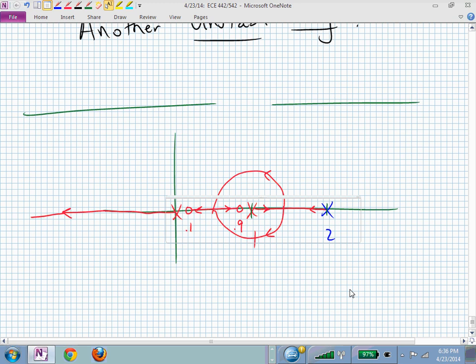And probably if I would squeeze those together and make this one not 0.9, but maybe 0.7, and the other one maybe leaving it at 0.1, my percent overshoot would probably improve. But I need to be careful that I don't go zipping with that third branch outside the unit circle when I crank up the gain. And you could check that differently than the way I checked it if you were doing it with your calculator. You could evaluate the gain at z equal to -1 and see if it's bigger than the 1.76.